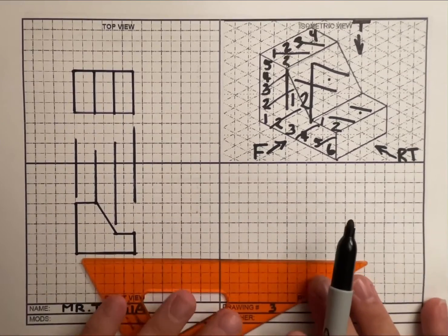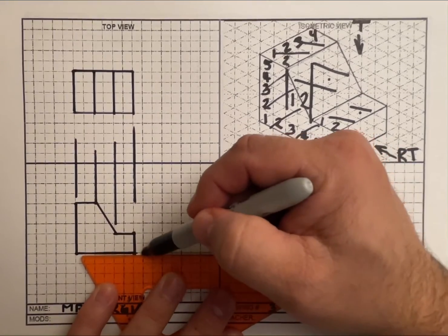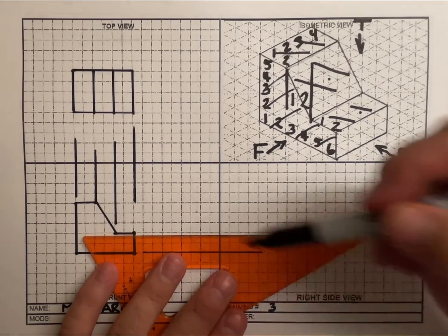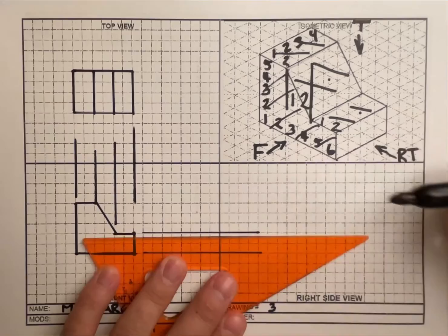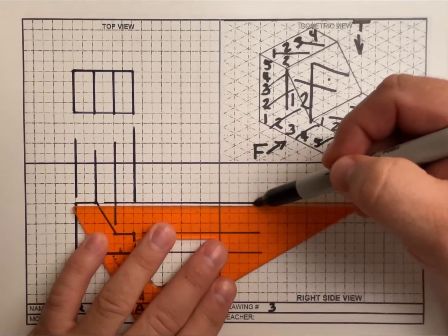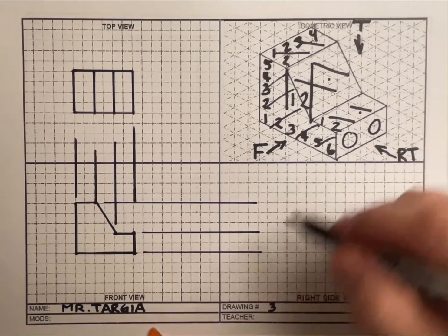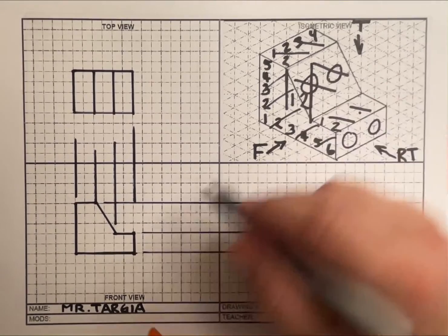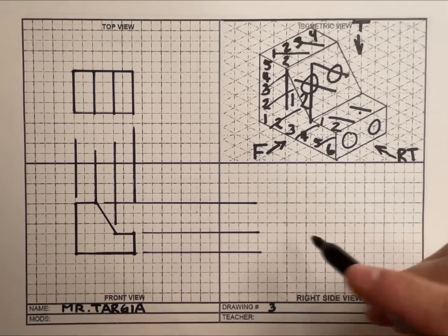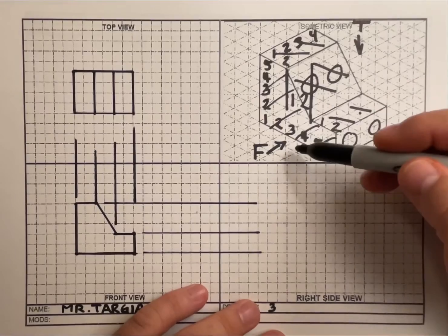And the last thing is the right side view. So I'm going to place my straight edge down here like so. I'm going to draw my projection lines over to the right side grid. I'm going to project this step. I'm going to project that over, and also I'm going to project the top that comes over like this. Now on the right side view, I'm going to see this surface area here, and I'm going to see this surface area here, directly on top of this one. Okay, so it's still 4 squares wide, and it's still going to be 5 squares tall.